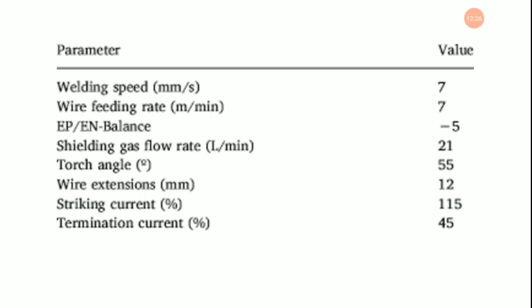This is because at low IP up to 200 ampere, the heat input is less and it is not sufficient to melt base metal with the filler material. The peak current more than 200 ampere gives more heat and it melts the base metal with filler metal completely and increases face width. So peak current plays an important role in the determination of face width value. As the base current increases up to 98 ampere, the face width value goes on increasing, and after 98 ampere, with further increase in IB value, there is a decrease in face width value.